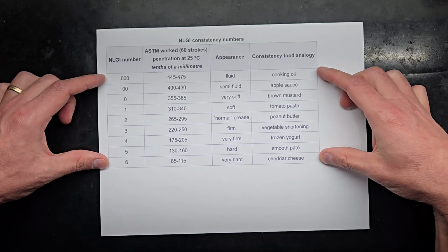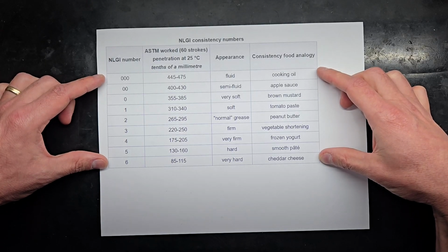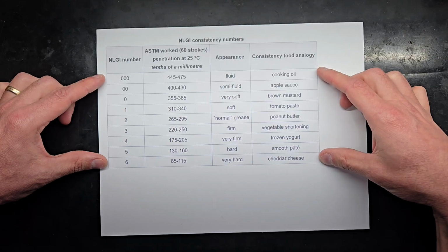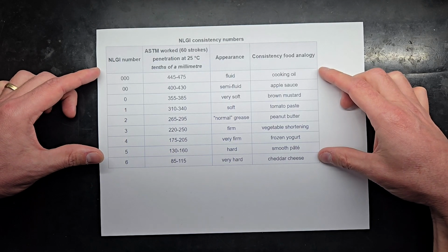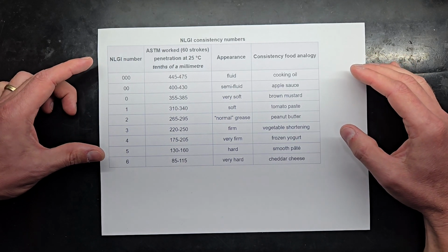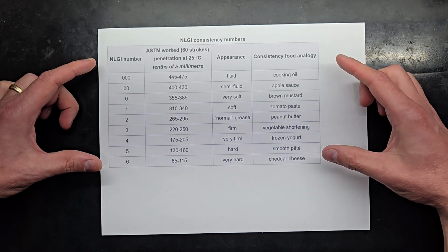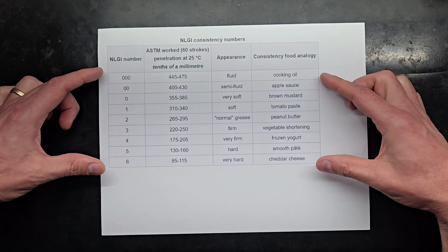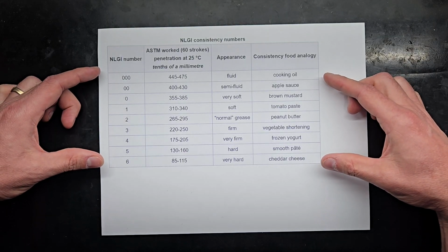And so in many of the firearm conversations that I've heard, people often say, you can't use grease, grease is too thick. And so just as I was talking about with the mineral oils, one way to tell how they don't know what they're talking about is if somebody says grease is too thick for a firearm, ask them what NLGI number grease they're referring to.